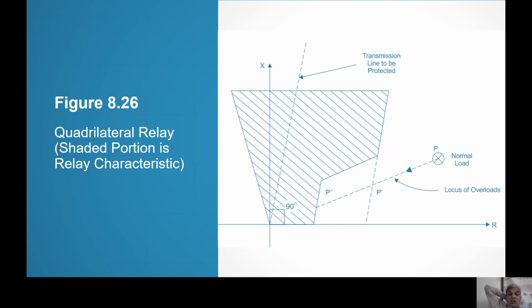The relay should not trip, relay should not operate, relay should not trip the breaker because this was not a fault. So you have to take some actions. So one action you can take is that the third zone reach has to be properly designed. Third zone reach cannot be very large. But in this quadrilateral characteristic, people have done a very good thing. They have kept a notch like this, you see. This notch gives the advantage.